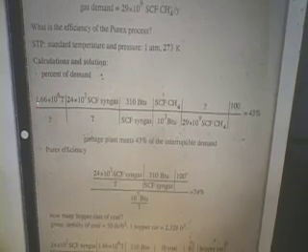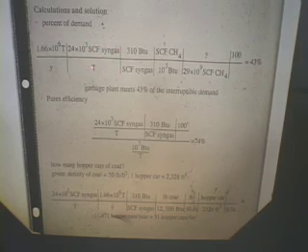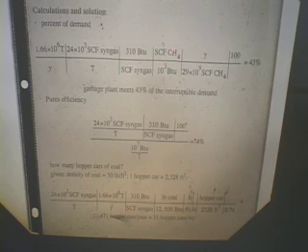And here we have 1.66 times 10 to the 6th tons per year of municipal waste. We know that we can get 24 times 10 to the 3 standard cubic feet of syngas per ton of waste. We know this is the heating value of syngas from the previous page. We know that this is the heating value of methane from the previous page. And here is the gas demand.